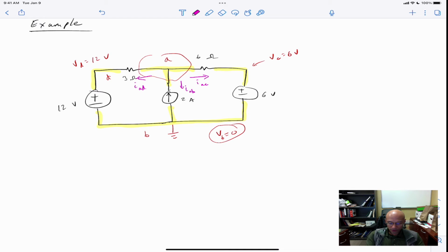Now, from Kirchhoff's current law, those currents must sum to 0. One thing I'll point out here is that I have complete control over the currents that I choose. They're an arbitrary choice. However, I need to be consistent about how I treat them. So when doing Kirchhoff's current law, I need to pick a formulation like all currents leaving algebraically sum to 0. So I chose all currents leaving the node A, right? So let's just write out an equation. Those have to be equal to 0.